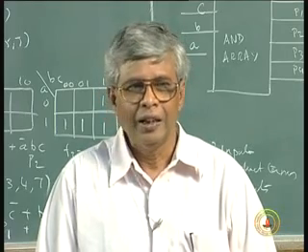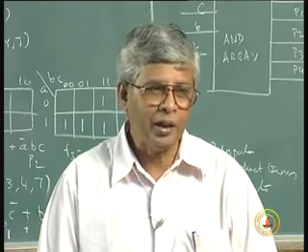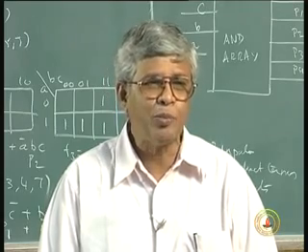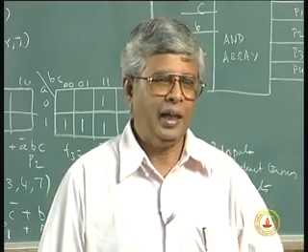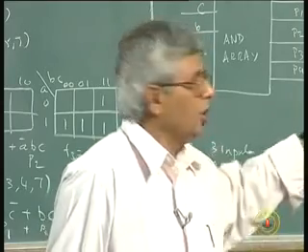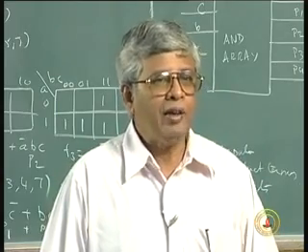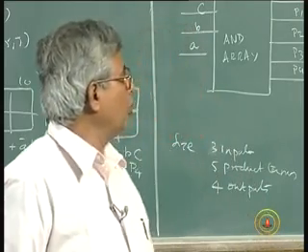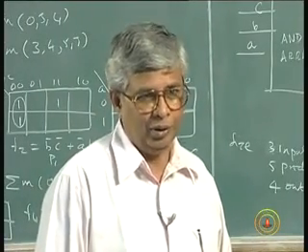So the outputs are programmable in a sense. Everything is programmable. Product terms are programmable and outputs are programmable. What is programmable is which of the product terms you combine. I can have up to 5 terms in each of my outputs, and that can be any combination. I can have F1 equal to P0 plus P1 plus P2 plus P3 plus P4. Again, F2 equal to P0 plus P1.